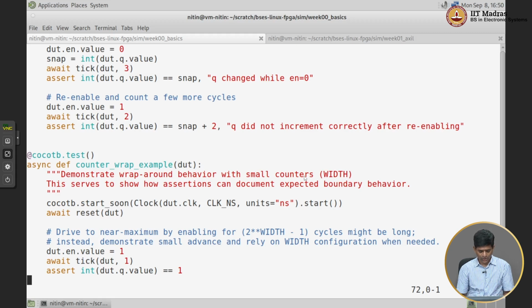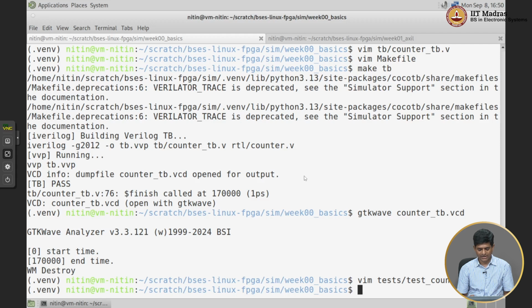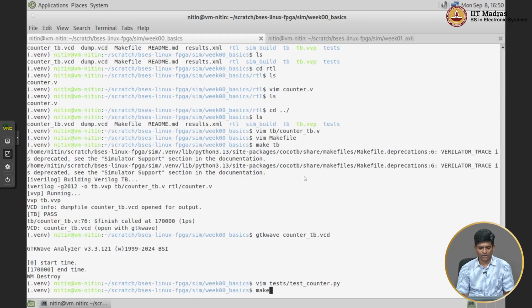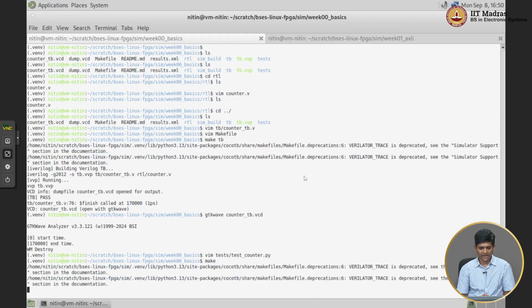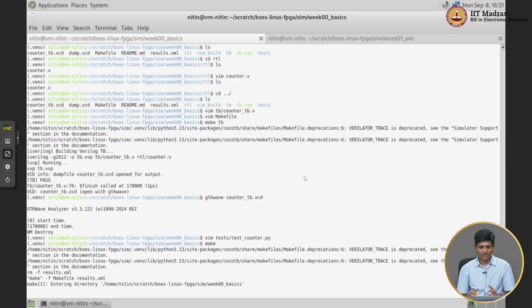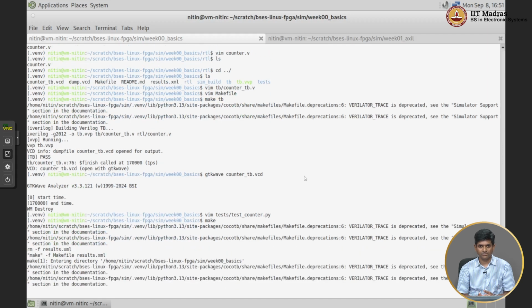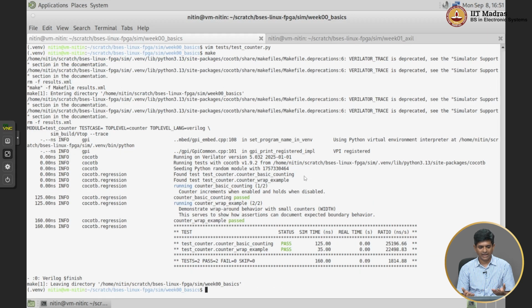Okay. So, anyway, how do I run a test like this? I would just run make, which by default in this case is actually going to run the Cocotb test bench. Now, one problem with that is by default this thing prints out a lot of information. So, I am sort of making the screen a bit more compact, and then I type make, it goes ahead, compiles all the code, right, appropriately, and then runs through and prints out a whole lot of messages.